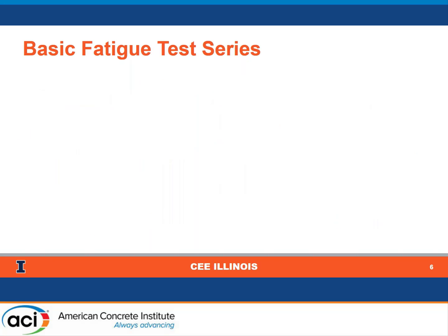So the next thing, having obtained the monotonic results, we started with the next test series, the first one of which was known as the basic fatigue test series. So I'll give a very brief description about this test series here. In general, in this test series, we tested concrete cylinders under fatigue loading in uniaxial compression.